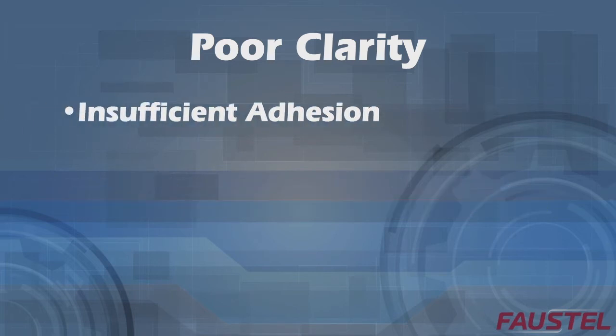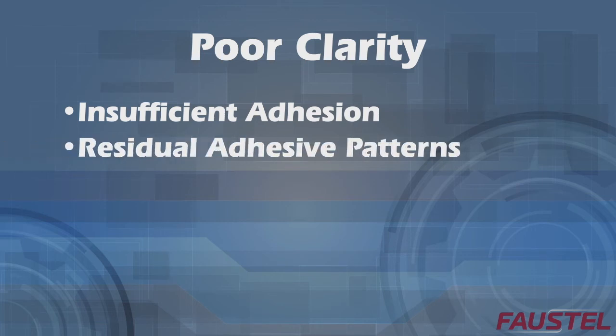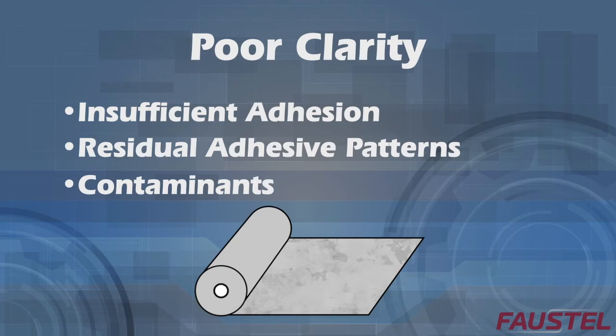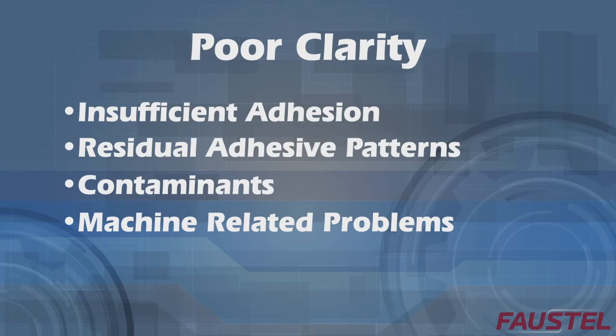Causes of clarity problems include insufficient adhesion to the secondary web, residual adhesive patterns resulting in high and low points which are not flattened in the nip, contaminants in the adhesive or on the web, and machine-related problems such as roll bounce, dirty roll surfaces, inadequate nip pressure, or insufficient roll temperature.